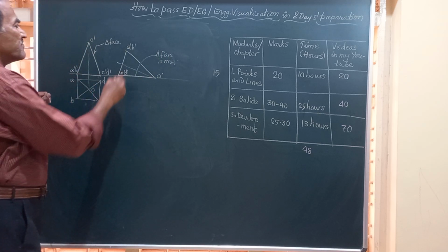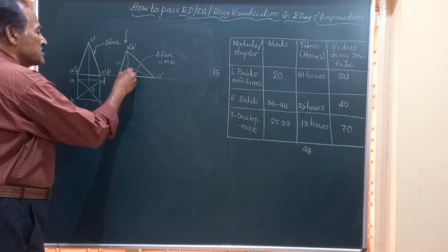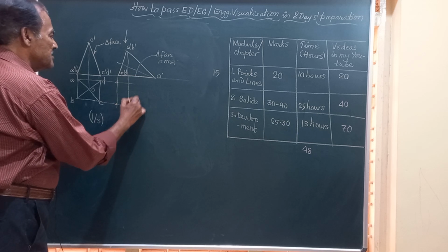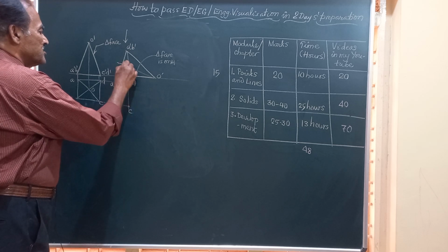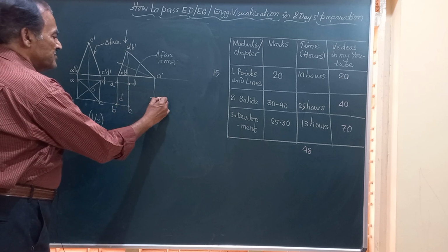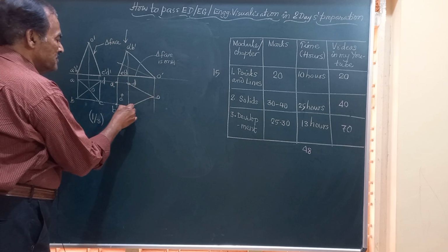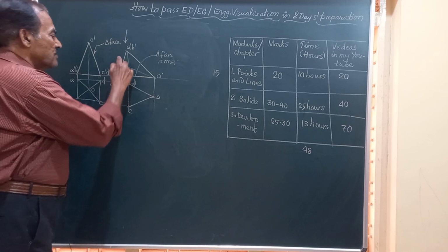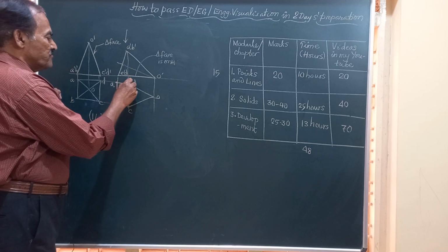So corresponding to that, friends, if you look from the top, you will be able to see the complete base, that is A, B and C, D. So this is point A, point B, point C and point D. I will mark it as A, B, C, D. And this is O1 in the center. O is the vertex. I will locate the vertex here. Join this vertex to all the corners of the base. And here, friends, I would like to give you a very important tip. Now the complete base is visible, so let me darken it first. Show by visible lines, all these.